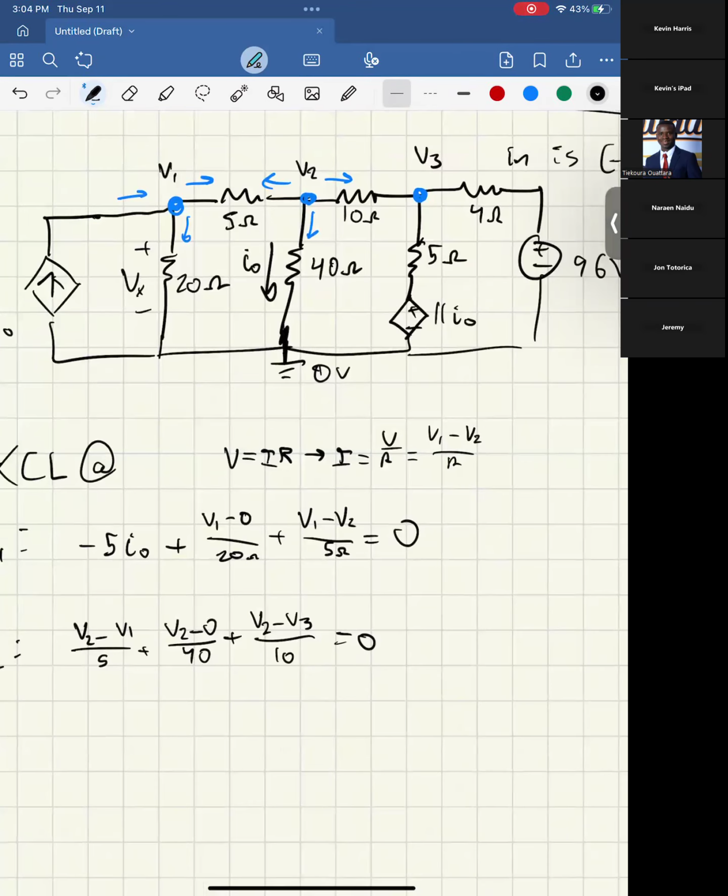So with what you were saying about the arrows pointing in opposite directions, if we look at this term and this term, in the first equation we have V1 minus V2 over 5, and in the second one, we have V2 minus V1 over 5. This one equals the negative of that one, right? Because you just flip these around. And what that's telling you is that even though in our math we're saying that both of these are going out, one of them is in the opposite direction of the other one. We don't know which one yet, but we know from our equations that one of them will be the opposite of the other, so this will still work.